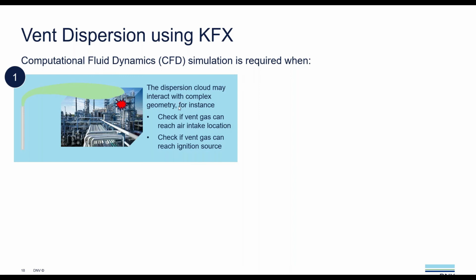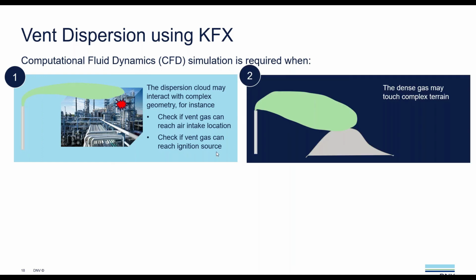You might want to consider using KFX when your dispersion cloud may interact with very complex geometry, and you want to take that into account to check if my vent gas can reach an air intake location, or whether my vent gas can reach the location of an ignition source, because we don't want the cloud to be able to ignite. We can also consider if my dense gas cloud will interact and reach an area of complex terrain.